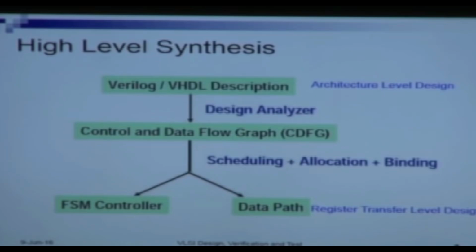However, if we look from the perspective of an entire embedded system, all these processes we may not need to implement in hardware. Some of them it will be sufficient for us to implement in software, which means that for those blocks of code, we will only use a general purpose processor and execute a high-level program like a C language program for that process and run it, and that will be sufficient.